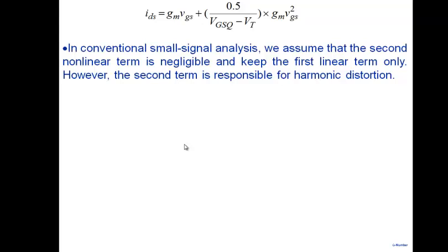If you want, I can write down my amplification like this here. I have small signal VGS goes to IDS, and then this IDS goes to V0. Note that this relationship is linear. V0 is nothing but IDS times RD. So this is linear. No distortion occurs here. Distortion occurs because of this part here. Okay, that's where the non-linearity is. So that's why I'm calculating what is the distortion in IDS. Whatever is the distortion in IDS, the same distortion will be in V0. There's no difference between the two.